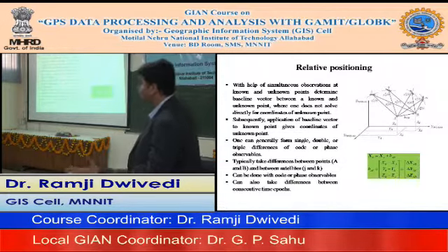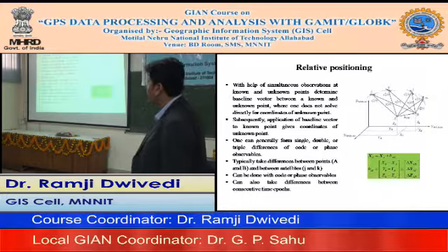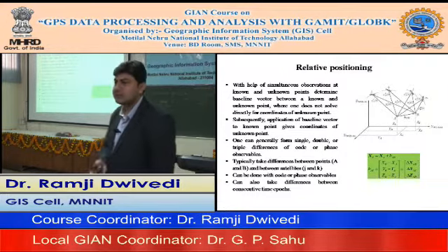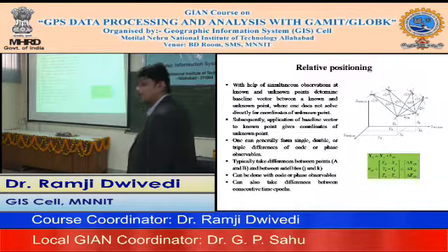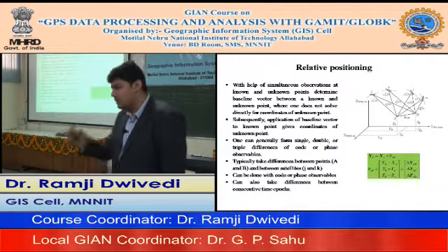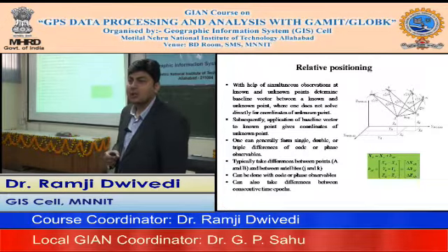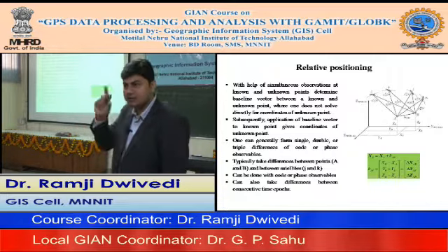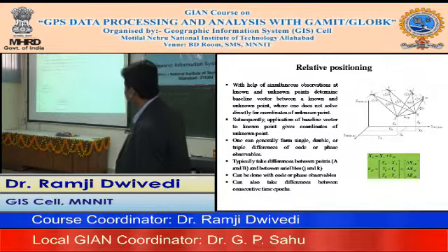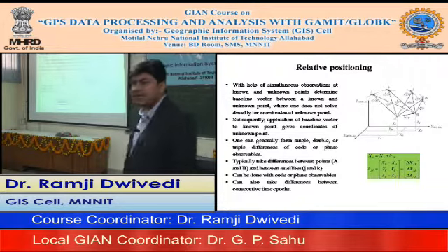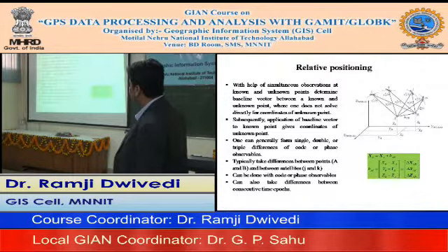One can generally form single, double and triple differences, which are the backbone of understanding relative positioning. We'll see what those single, double and triple differences are, and which one we prefer. You will see that in your GAMIT manual also, where differences are written in the first few pages. Try to read that part also. So we use the measurements of this baseline vector to estimate our position, because we have a good estimate of XA. Here, in the differencing of observables, the word relative comes.